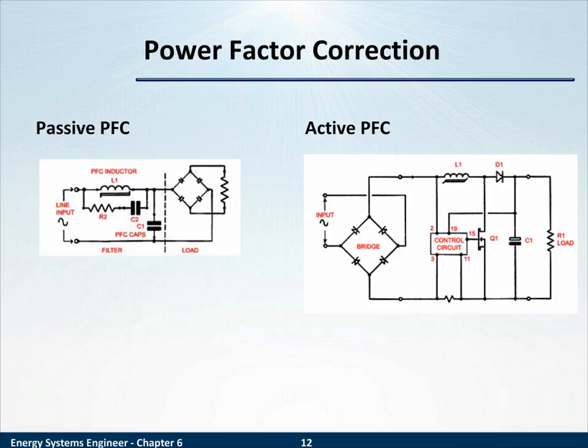That said, however, there are some stratifications, some layers, like with chiller sizing, that can help put power factor correction in context. The first is for small power supplies, let's say less than 100 watts. The most common type of PFC, power factor correction, is passive. Passive PFC uses what's known as a harmonic filter, filtering out harmonics, placed at the AC input, and it's used to correct power factor.